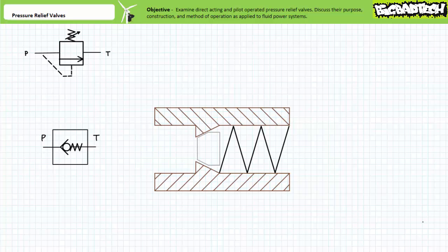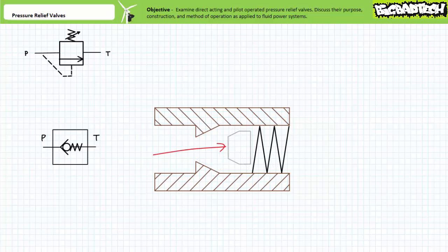Even in the ordinarily free flow direction, the poppet remains seated at load-induced pressures below that sufficient to unseat it, and the direct-acting pressure relief valve remains closed. Only at pressures above that sufficient to unseat the poppet from the seat, the valve opens and provides a relief path for pressurized flow. Pressure in the system is therefore limited to a preset maximum.